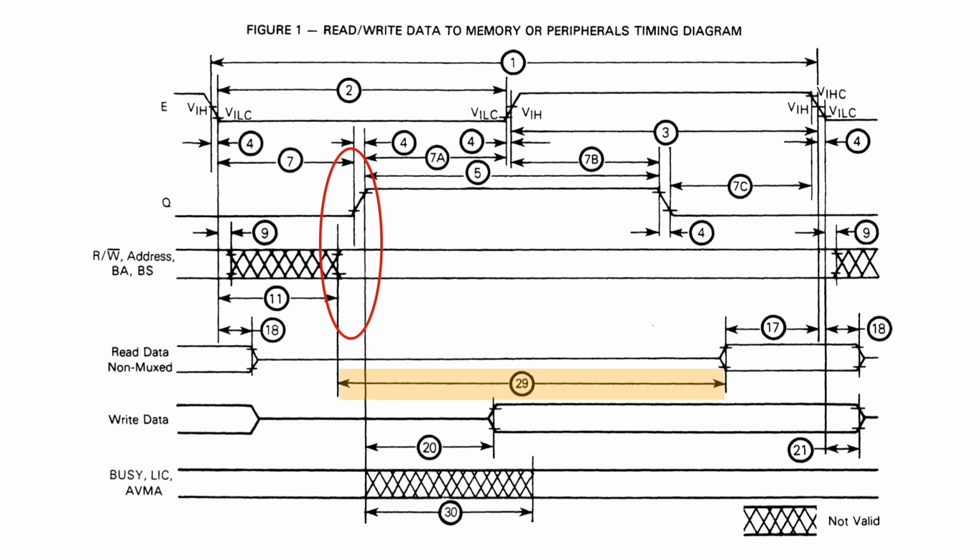Now, on a read cycle that's issued by a 6809 running at 2 megahertz, from the moment this information becomes stable, we have roughly 330 nanoseconds until the data has to be valid and the data bus stable in order to meet the 6809 setup time. Now, if we're going to try running a 6309 at 4 megahertz, we only have 165 nanoseconds.